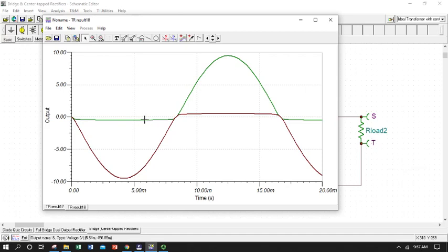So if we wanted to plot out the load voltage, we would literally go through and subtract these 2 curves from one another. And when we do that, we're going to get the influence of that second diode in each direction in the form of this small offset here. So one way we can do curve subtraction or addition is to go to the post processor.